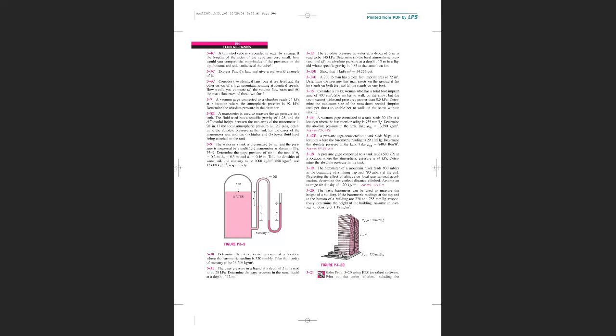We said the best way is to approach this from here, because this is atmospheric pressure at the end since the tube is open. Going down, we said, when analyzing manometers, going down is positive and going up is negative. You can move from 1 to 2 or from 2 to 1. If you move from 2 to 1, you have P atmospheric plus